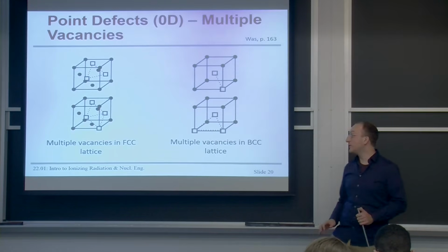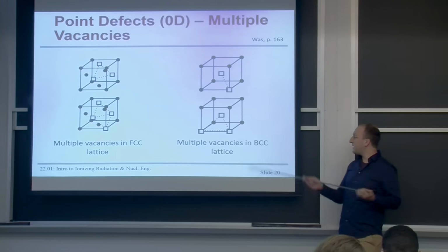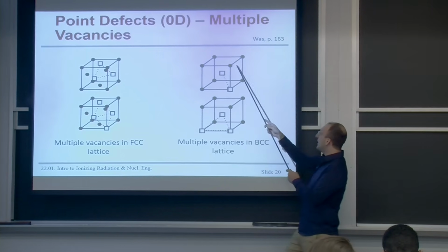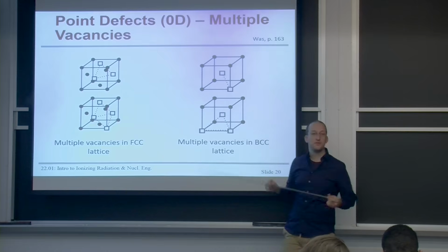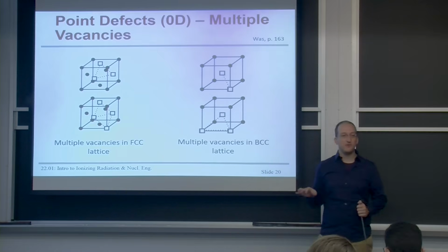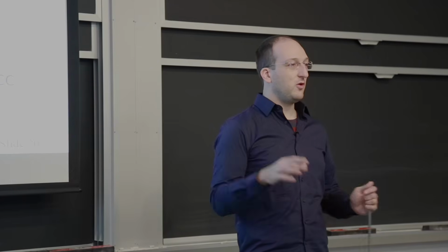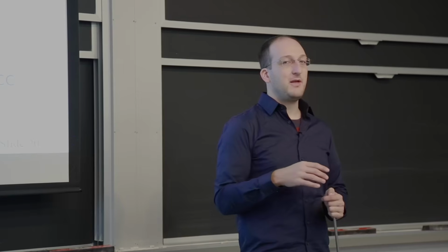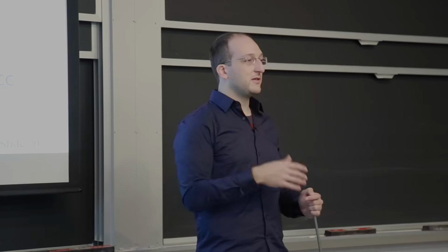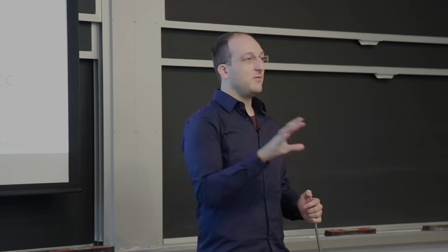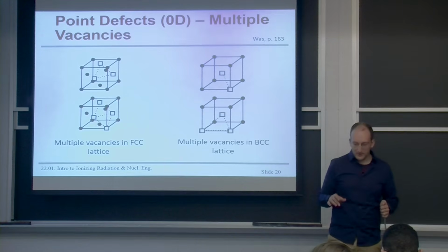They can also cluster up. It turns out that every time you have a vacancy in a material, the other atoms move in a little bit towards it, relaxing the pressure they feel from the atoms nearby. And one way for a whole bunch of vacancies to lower the stress of the whole atomic configuration is to cluster together. So if you have a whole bunch of vacancies, they may not allow as much stress accommodation as if they were separate when they're together.